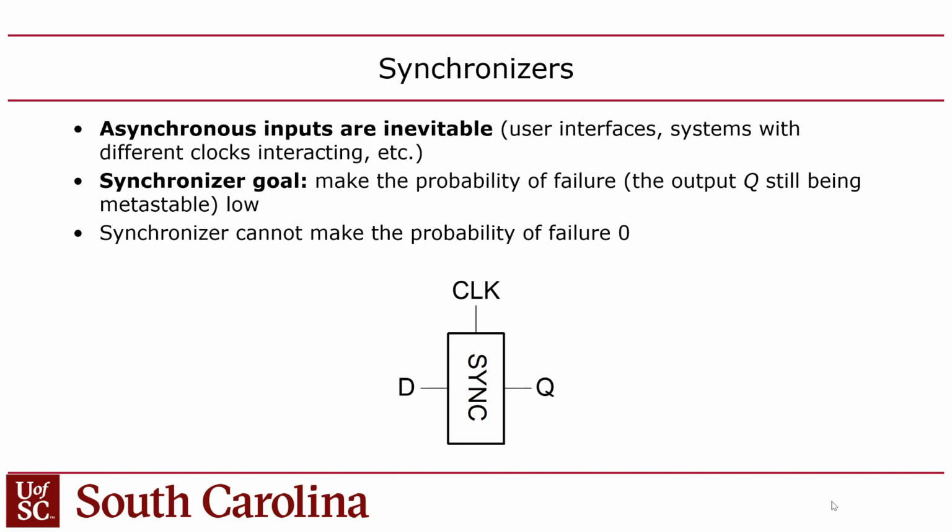Now you might say, wait a second, why don't we just consider the first flip-flop the synchronizer? Well, you don't want to do that because you might have some logic before that, right? The goal here is to have a whole clock cycle. The objective is to have a flip-flop with nothing after it going into another flip-flop, because that gives you that whole clock cycle with no logic. You don't have to worry about logic in there. That gives you the whole clean clock cycle for that first flip-flop to get out of it. The whole point is not to have anything between those two flip-flops, because then you maximize the amount of time that the random variable that determines the metastability time has to get out of it. And that's the whole point of a synchronizer. Now, it's not a guarantee, though. There's no guarantee that you won't fail and violate the dynamic discipline by virtue of just having someone hit a button on your computer.